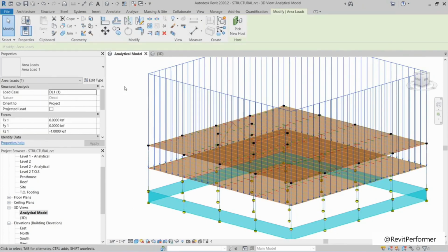So when you're modeling stuff in Revit, and you're thinking about doing structural analysis using your Revit model, a lot of times this stuff needs to be filled out. Generally it will be if it's a material you use that came with Revit, but if you create your own material, there's a chance you'll have to go through and change these properties.